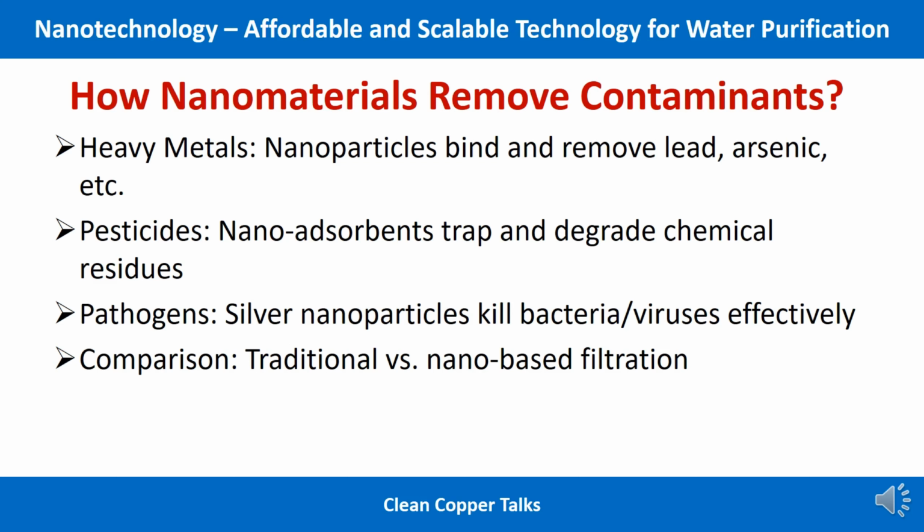There are research articles throughout the world, even in developed countries, where such emerging contaminants, let's say antibiotics, pharmaceuticals or microplastics, or the conventional parameters, or heavy metals such as lead or arsenic, pesticides, are found in very small quantity. The problem with them is they are deleterious to human health even in very small quantities, such as microgram per liter to nanogram per liter.